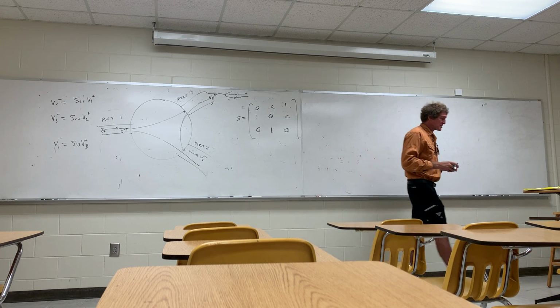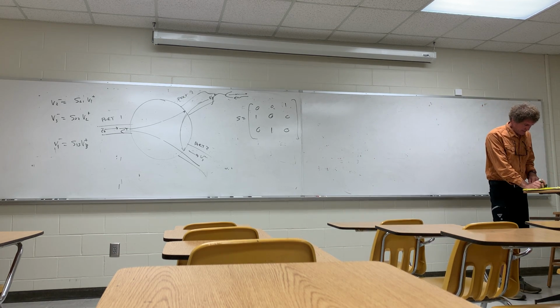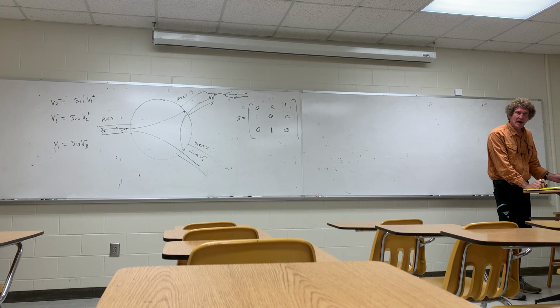And Dr. Wentworth shows in his book something he believes is a typical representation. So he says the insertion loss is 1 dB for a circulator, and he has a VSWR of 1.5, and he wants the actual S parameters, and so he does get them from there. But I tell you the truth, I don't worry about dB. I may give you some problems with it. Mainly with the circulator, I always think about the linear value of the S parameters. You can back them out from the values in dB easily.